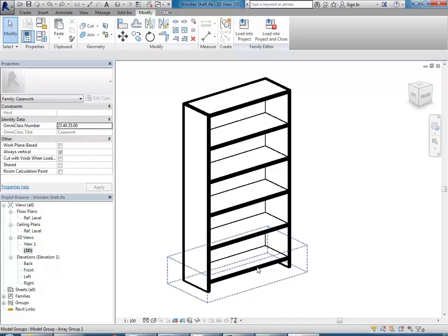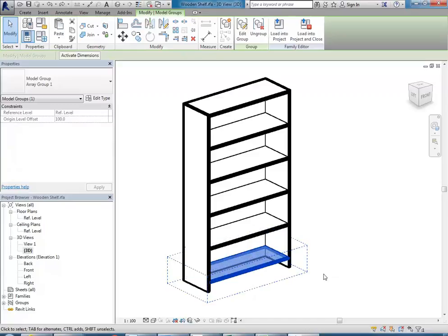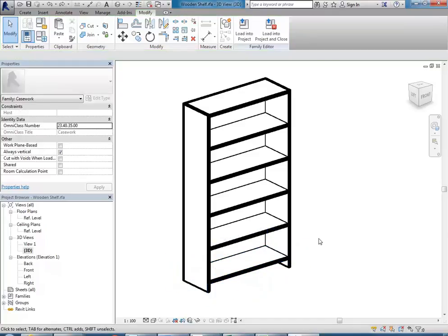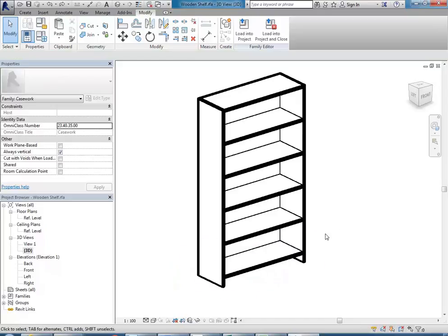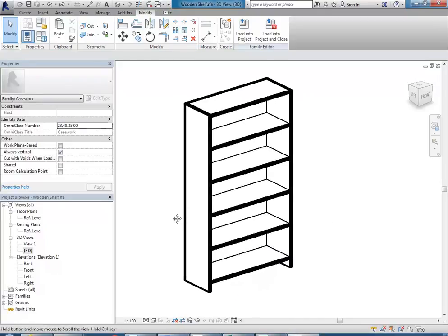And so by making this shelf into its own family, I can give it its own properties of width, depth and height. Then when I bring it into this family, all I need to do is plug those parameters into the shelf's parameters of width, depth and height, which I'll show you later. But that's going to be the thought process. Anyhow, we'll get into nested families fairly soon, hopefully. But like I said, that should be plenty for now to get started.